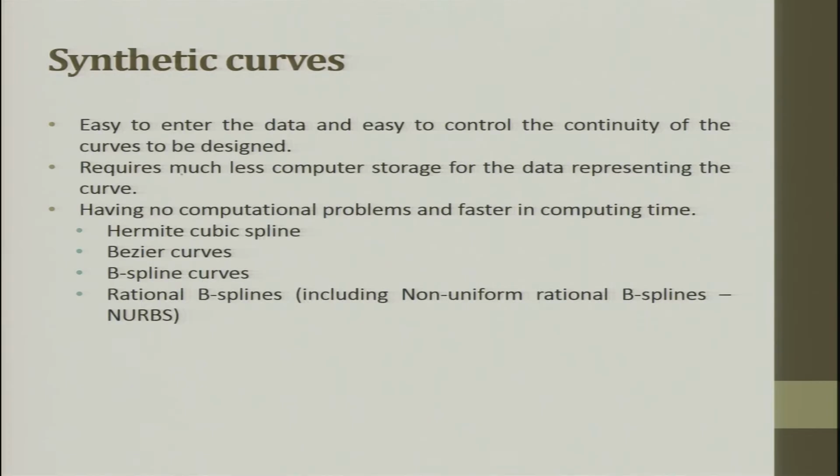So, whatever we studied till now, we studied curves, then we studied the data points which are generated, and from those data points we are trying to form these curves. So, these things which cannot be mathematically represented are called synthetic curves. Curves can be divided into two: one is analytical and another one is synthetic. Analytical means where there is a clear definition of equation available. Where there is no clear definition of equation available, we go for synthetic curves.